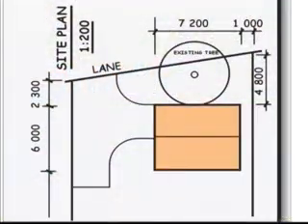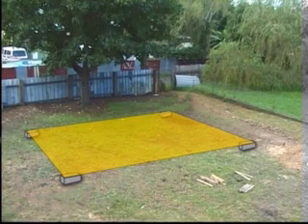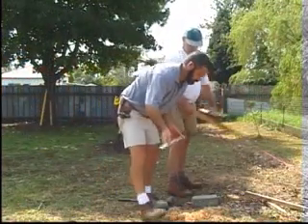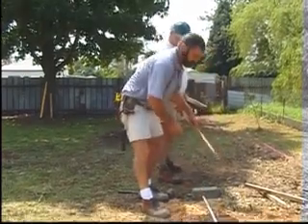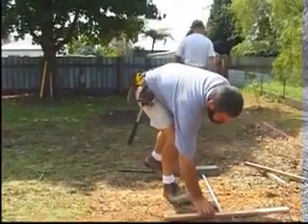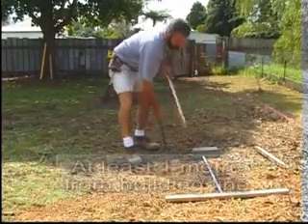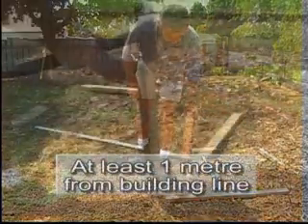The side of the building parallel to a boundary is set out first. With the approximate siting of the building as a guide, a pair of profiles is set up to carry the string line for this first side. To allow ease of working and access for machinery, profiles are placed about 1 or 2 metres outside the line of the building.